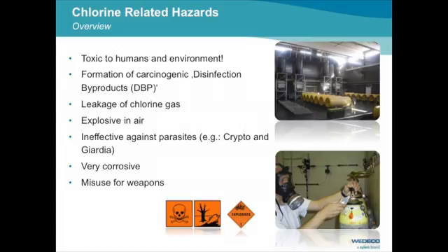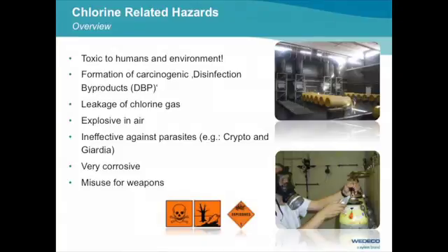Another main concern is the formation of disinfection byproducts, which are typically carcinogenic and which are also difficult to destroy in the further treatment chain. It is explosive, especially in warm climates. You need to have proper cooling of the tank, and the transport also needs to be taken care of. If you count all these safety measures in, chlorine is not as cheap as it is perceived in the first place.